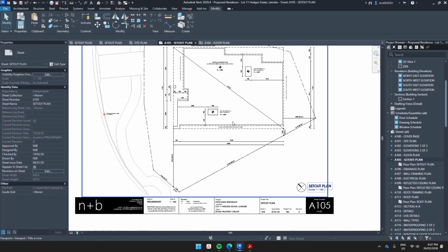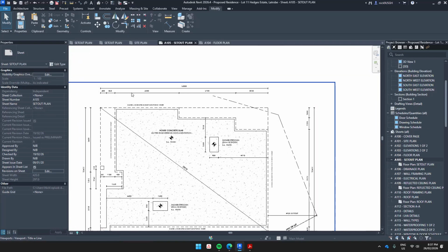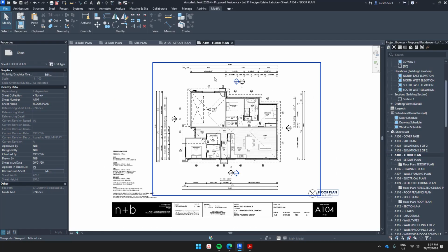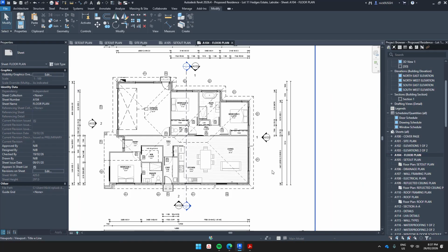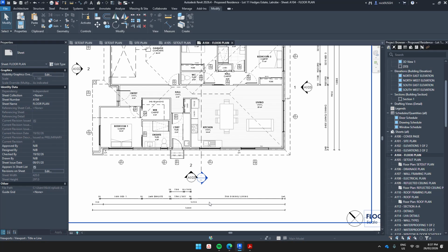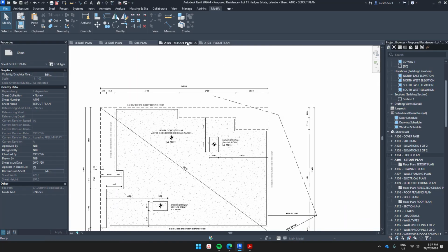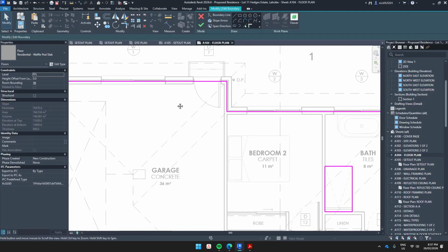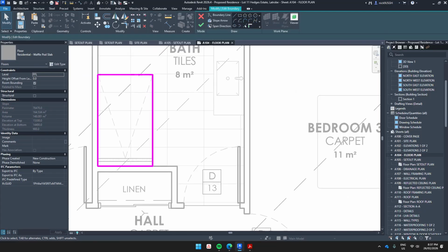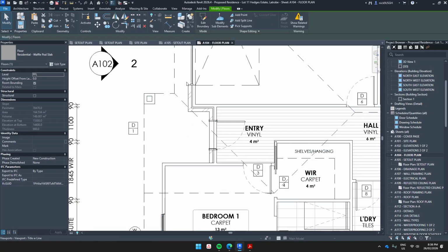That's our setout. So another thing to do is a cross check, just to make sure all these measurements are right. These overall measurements should match up to the overall measurements on the floor plan. So once again, if they don't line up, something needs to be fixed. So you probably need to check the slab line to make sure it lines up with the stud line. As you see here, tracing along here, everything seems to line up all right with the shower set down. So that all looks good.